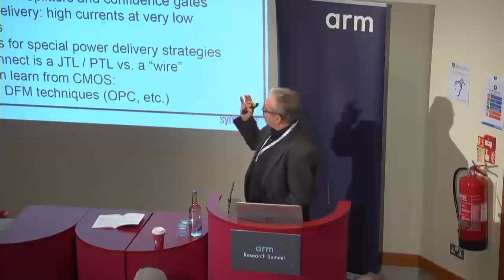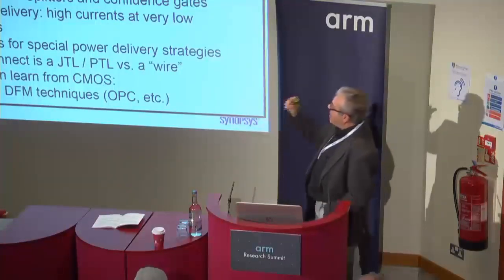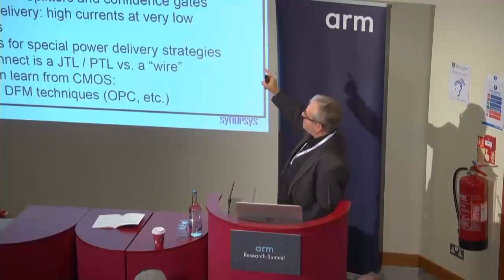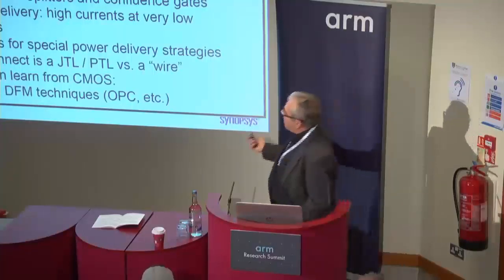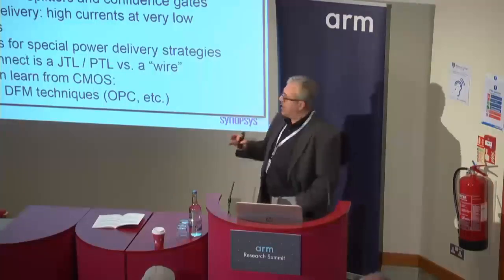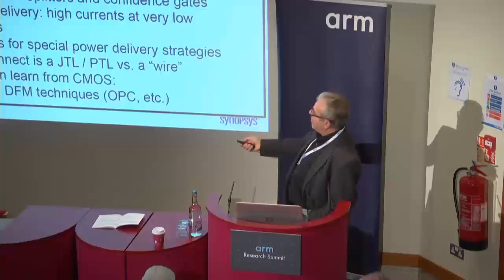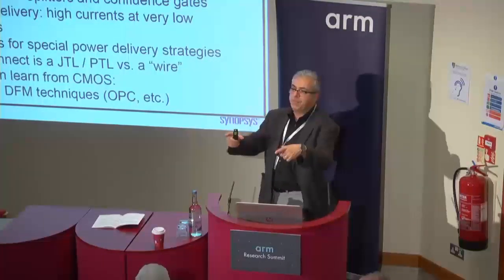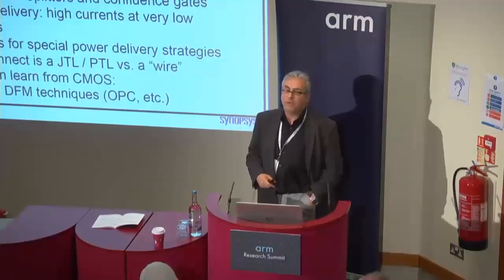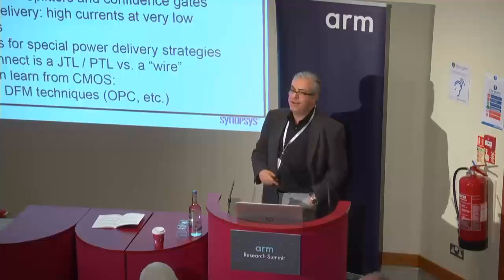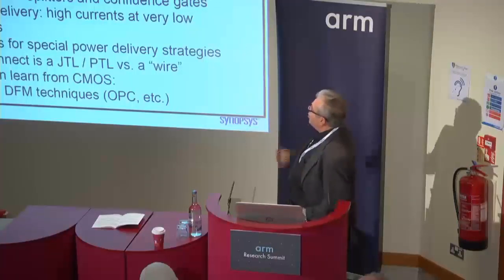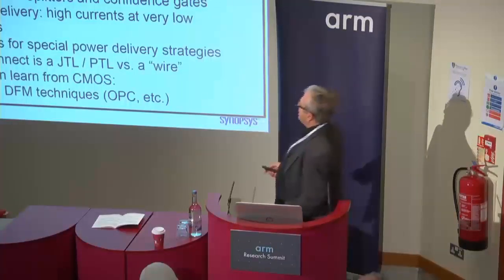You have to bias every Josephson junction in the design at a certain limit related to what's called critical current. Above that, it goes into resistive region and it's of no use to you. So now when we are talking about VLSI integration, theoretically, if we don't have design techniques that would alleviate the power delivery problem, think of this. Think of a chip with 1 million gates, 10 million Josephson junctions, that is going to need a bias current of 30 to 50 amps delivered at roughly 100 to 150 microvolts. That's a huge problem. It's not trivial, so you have to have techniques for realizing that.